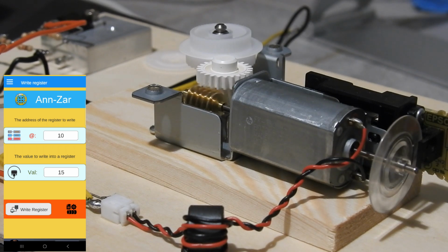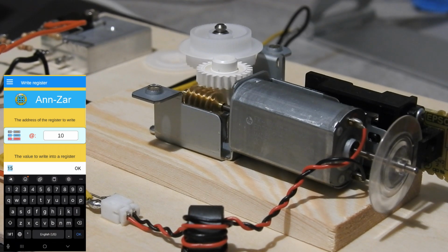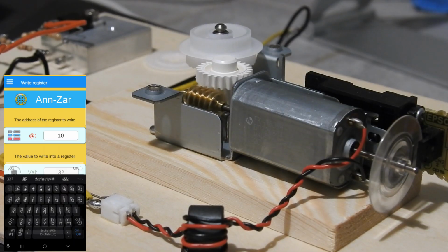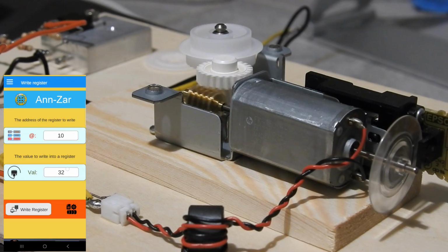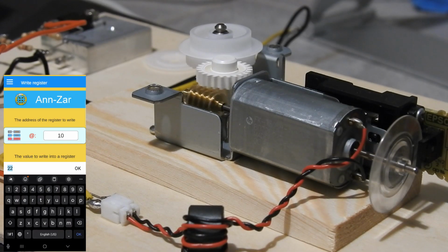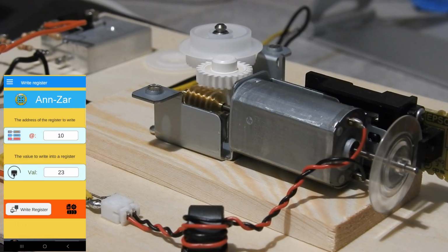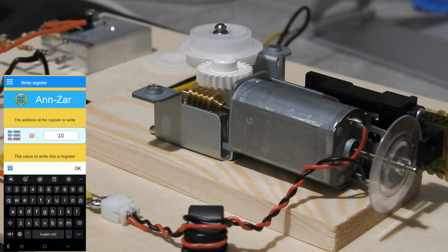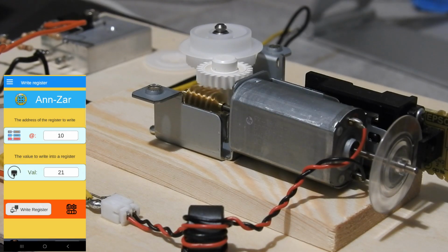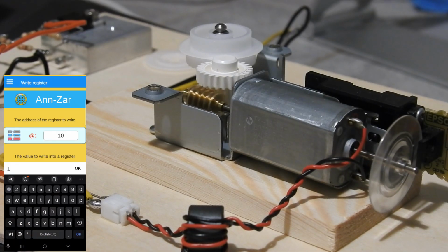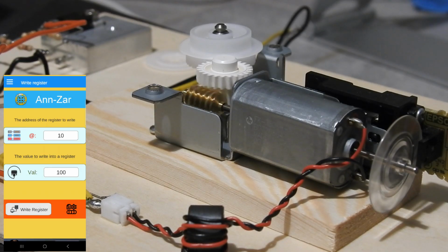Now we have reached the end of this project. We successfully controlled a 12-volt DC motor using a Schneider PLC M221, a PWM signal, and an IRFB4710 transistor power stage. We also implemented Modbus TCP IP communication to adjust the motor speed remotely using a smartphone. This project demonstrates how industrial PLC systems, power electronics, and network communication can be combined in a simple automation setup.